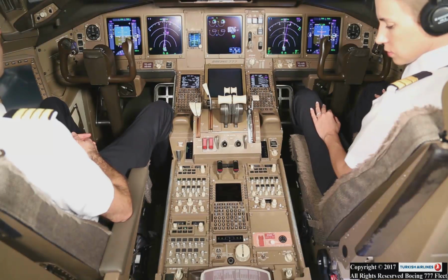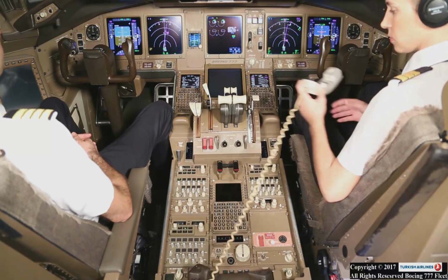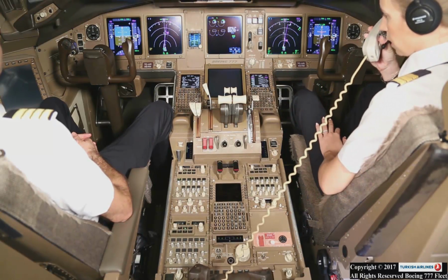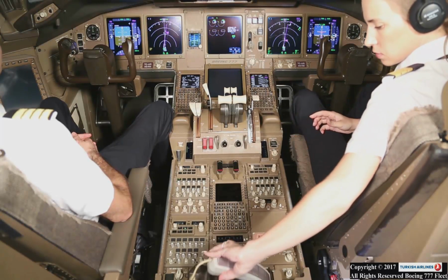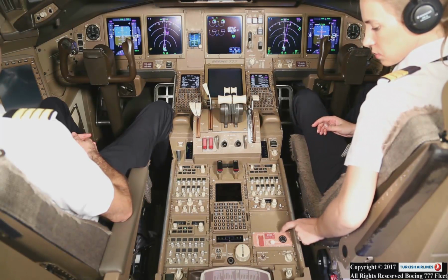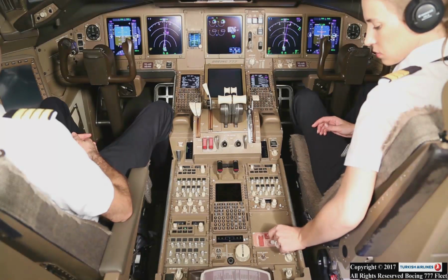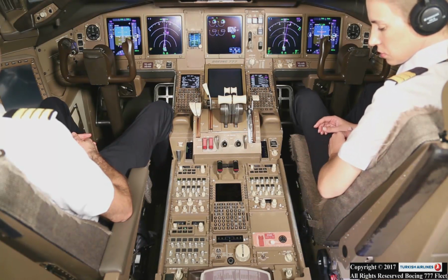Emergency evacuation system test. Inform cabin crew using the PA before performing the evacuation signal test. Cabin crew, evacuation test in progress. Evacuation command switch, door open, on. Verify the red evac light flashes and the audio horn sounds. Evacuation horn shutoff switch, push. Evacuation command switch, door closed. Get a report from the purser that the system works properly. Flood light switch, as needed.